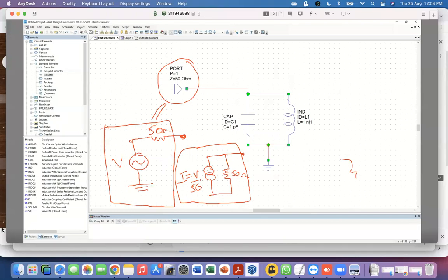You have to assume that there is some other measurement element connected across that 50 ohm, some idealized voltmeter. An ideal voltmeter has infinite impedance, so it can measure the voltage drop across that resistor, and that's how you detect.